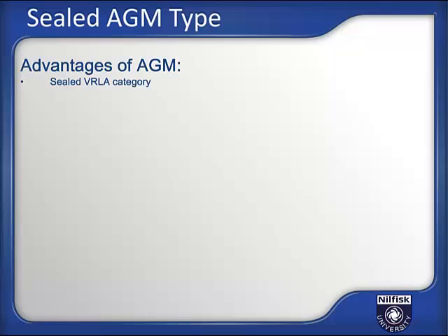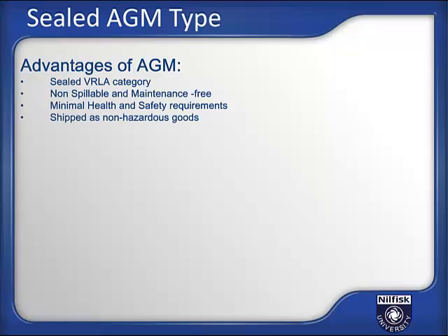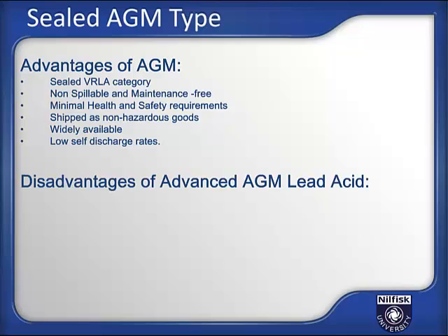First off, it fits into the sealed VRLA category, which means it's non-spillable and maintenance-free. This means minimal health and safety requirements, and it can be shipped as non-hazardous goods. This product is also widely available. It has low self-discharge rates, being a recombinant technology.